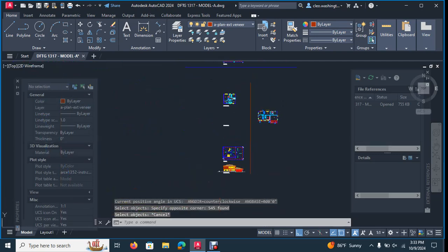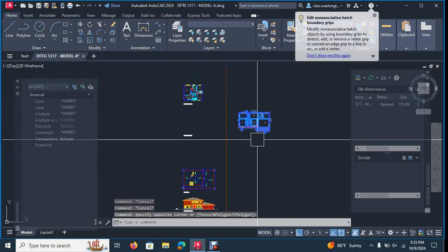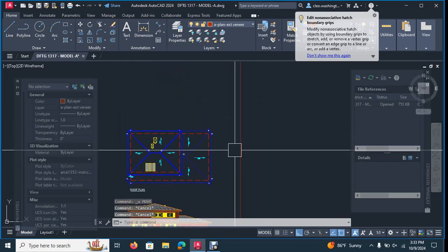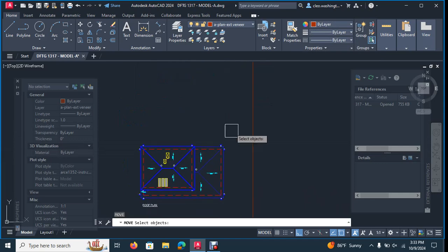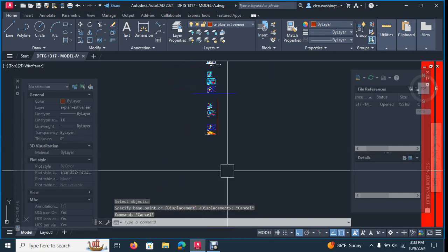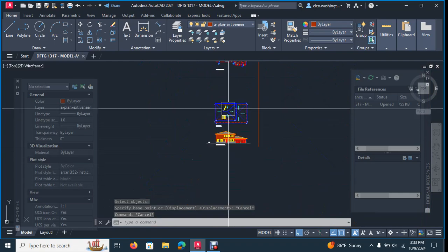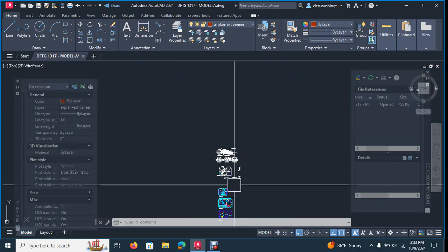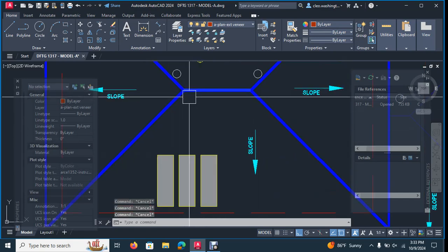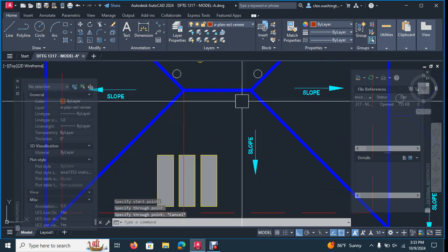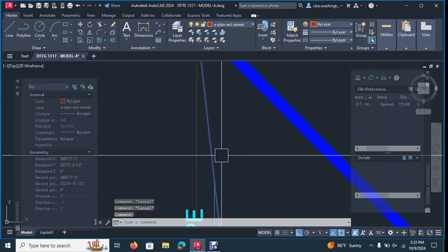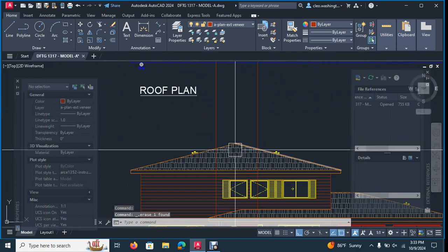And actually, to draw, I'll do something first. Before we do that, let's undo this. Once you have one elevation drawn, let's take the roof plan and move it back up. We just brought that down so we can project the roof lines down, okay? And actually looking at the roof, it seems like we need to make an adjustment here, and we do. I'm glad I caught it. See these pitches in this gable? Let's hit RAY and project these lines down. This is why I brought it down. See what I'm saying? These drawings always tell on themselves if it's not all the way complete or if you have something that's off.